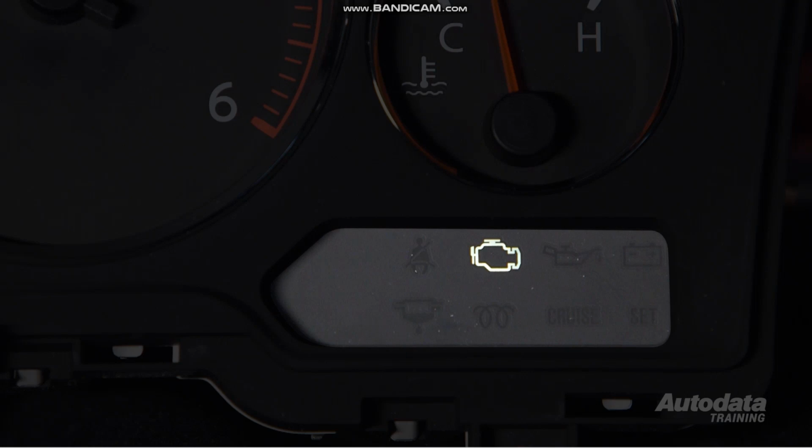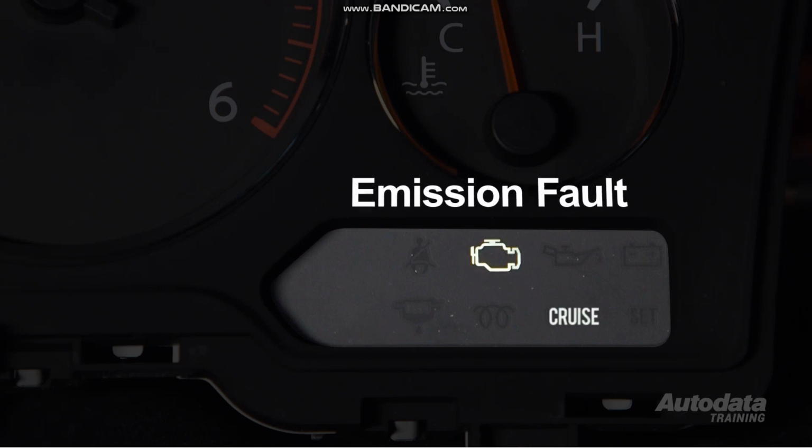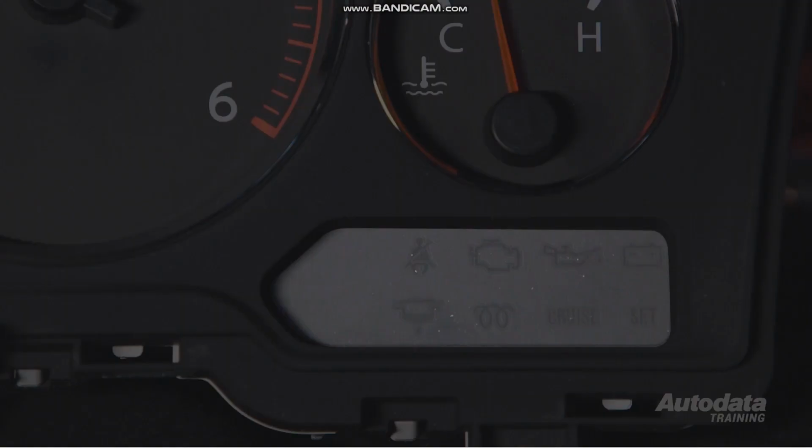Some vehicles don't use readiness monitors, but use a combination of lights on the instrument cluster for the same purpose. For example, a flashing engine and cruise control light to indicate an emission fault. Not all drive cycles are related to readiness monitors. For example, diesel particulate filter regeneration has a specific drive cycle, but does not have a readiness monitor. Instead, these systems will indicate by either a flashing or steady light on the instrument cluster.